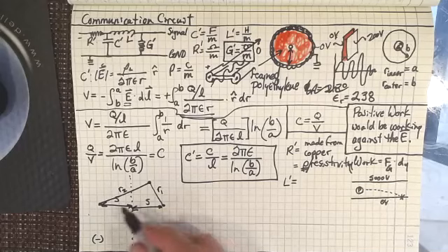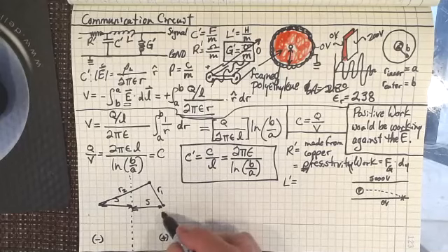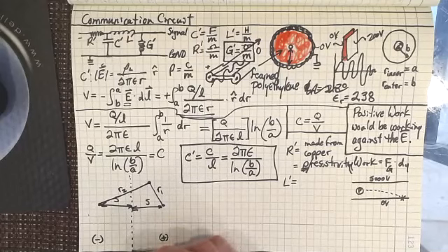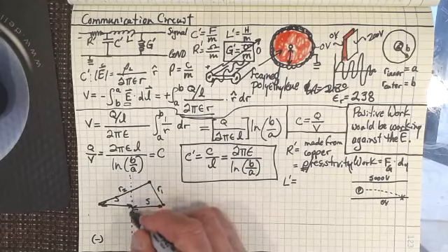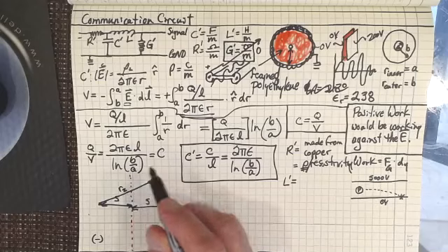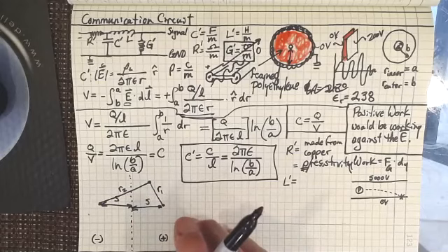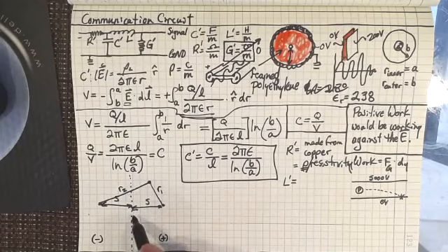So if I had 5 volts here and minus 5 volts here, then this would just be ground. This would be a central ground plane, wouldn't it? Right in the middle. I think everybody can see that. And so that's sort of why I've chosen this anyway. It's right in the middle of the two. It doesn't have to be 5 volts and minus 5 volts, but it's definitely going to be halfway of the voltage between those two. All right.